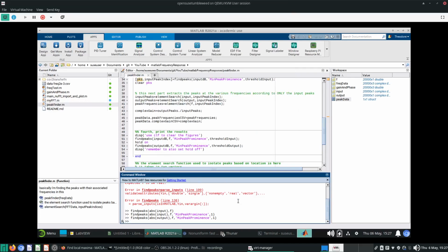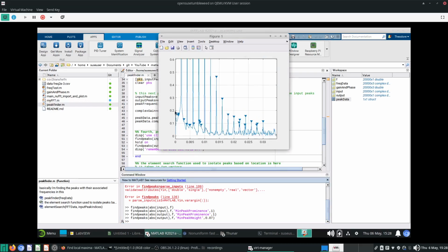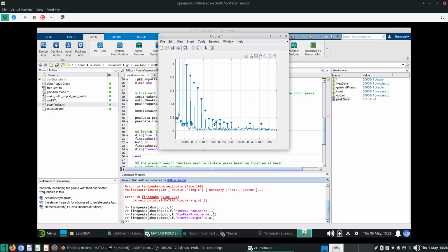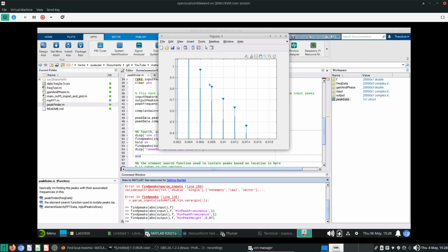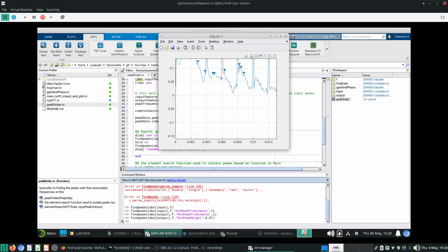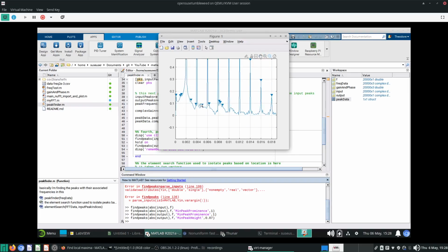So let me demonstrate to you. Okay, mean peak. If instead of prominence you use height, mean peak height, and you put 0.07, you'll see that a lot of places are going to be designated as peaks as well. So this thing is again oversensitive. It will identify all the other peaks also, but the problem is it's also detecting all of this noise as so-called peaks, which for our intents and purposes, we do not want to consider all of these peaks.